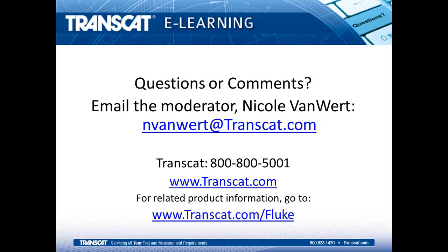The concern there is, without calibration coefficients for the probe, how do we know what the behavior of the probe is, unless that table has been generated for that probe specifically? If it's a generic table, I would use some caution there. I think it would probably be better to make sure that whatever table I'm looking at is in relation to that specific probe. If it is, then that's an acceptable way to do it using a lookup table. But you've got to make sure it's the table for that probe, because no two probes are the same.